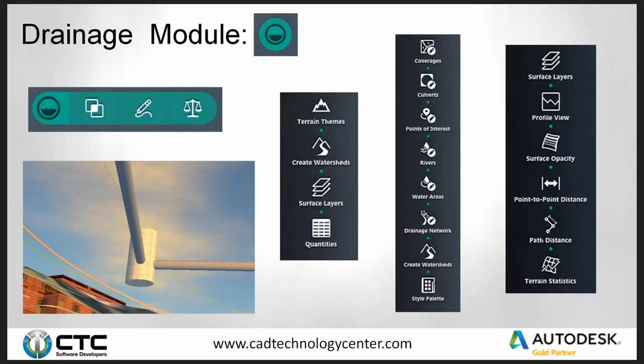So when I bring this model into Civil, it'll actually generate a pipe network using the out-of-the-box parts list. So no more do I see just a red line coming down to represent a structure and a red horizontal line to represent a pipe. I now actually see parts that are going to have identities, so when they come into Civil, they actually mean something. And the fact that I can actually get quantities from it.